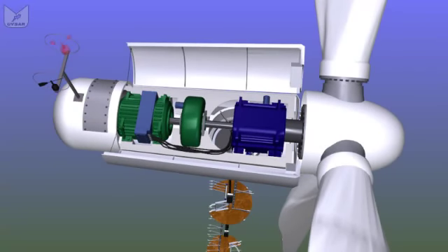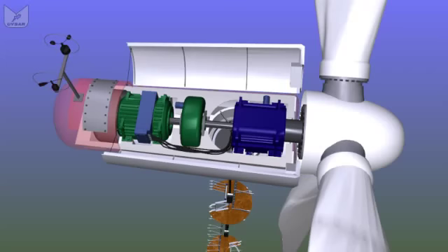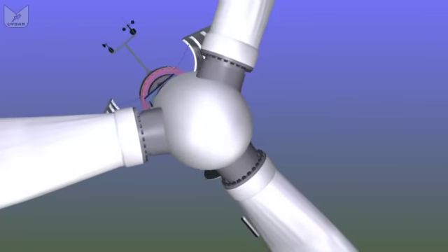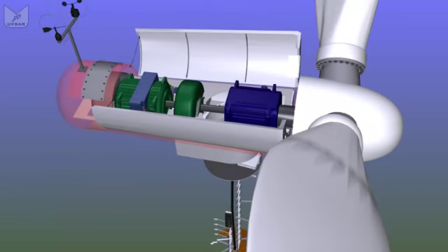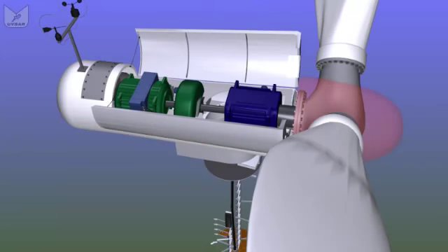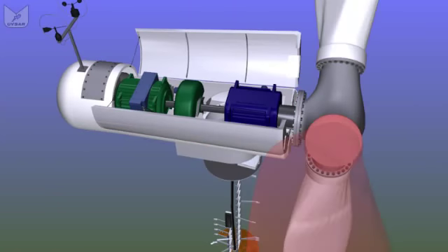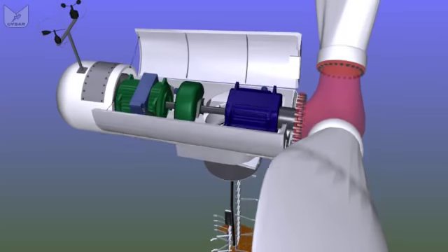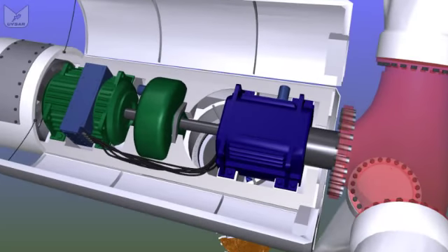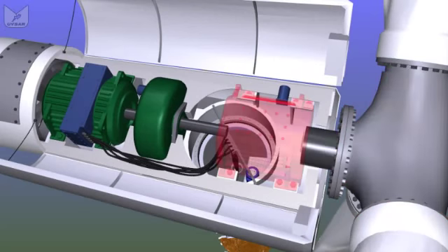At the back we have the wind sensors, which give us speed and direction and allow the turbine to face into the wind and to change the angle of the blades. The nacelle itself is just a fiberglass tube. At the front we have a similar fiberglass cowl protecting the hub, which is a steel casting on which we have bolted our three blades, and the blades can turn or pitch so that the angle they form with the wind can be varied.